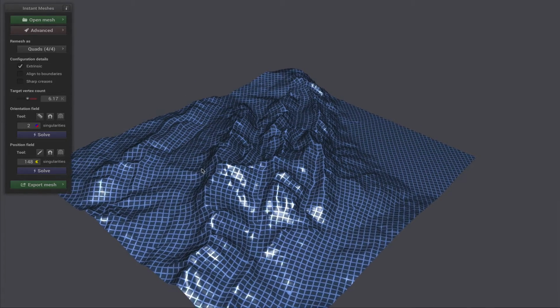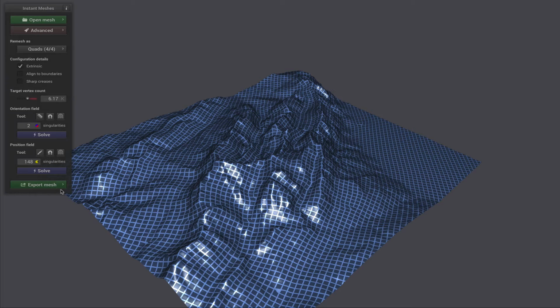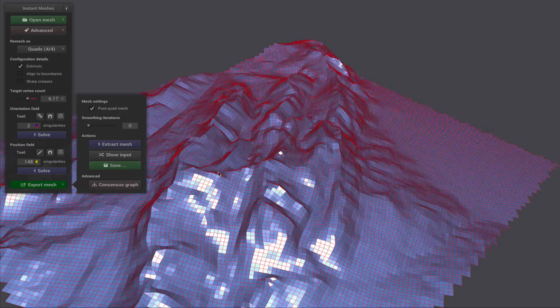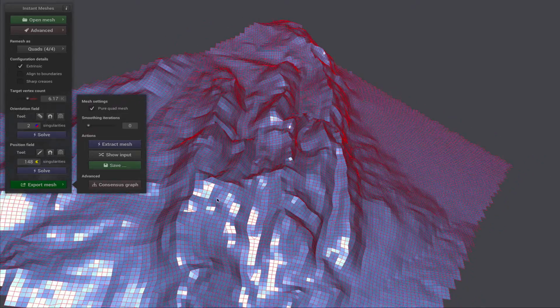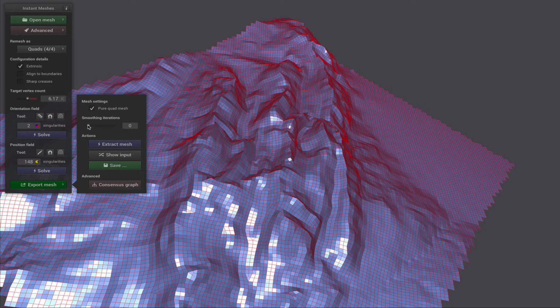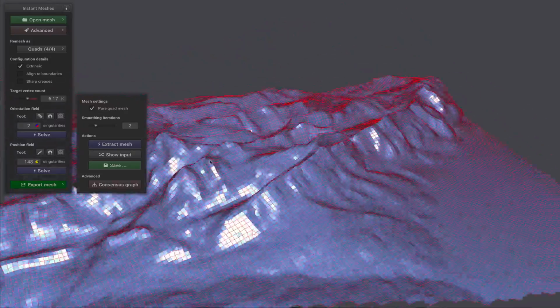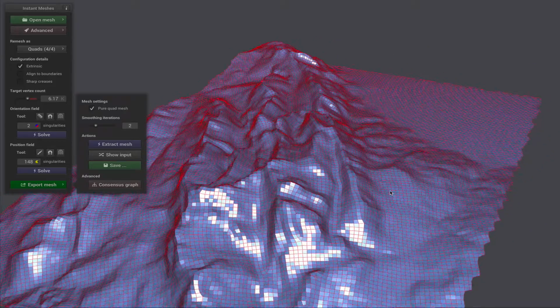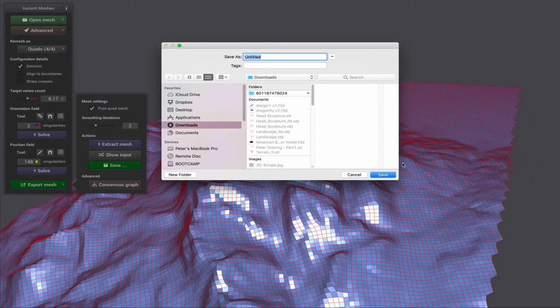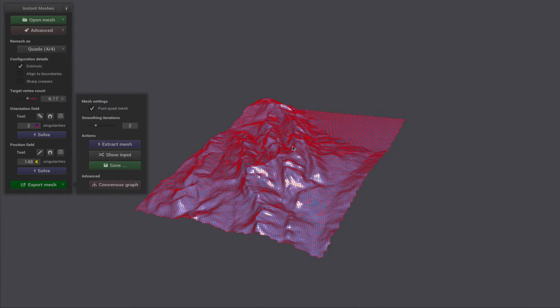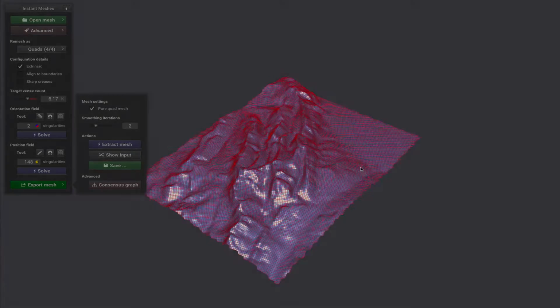I personally think this would probably be okay. So this looks pretty rugged, I'd say, and there's some pretty sharp corners in there. So I'm going to apply some smoothing iterations and click on Extract Mesh again. And that looks okay to me. So again, I could just save this out into yet another .obj file. And that OBJ file we would now import into Fusion 360.